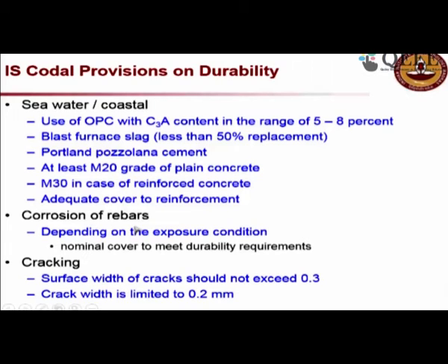Now if you are talking about cracking, there is a provision that the crack width at the surface of the concrete should not be more than 0.3 mm, and it is limited to 0.2 mm, and it should not be more than 0.3.